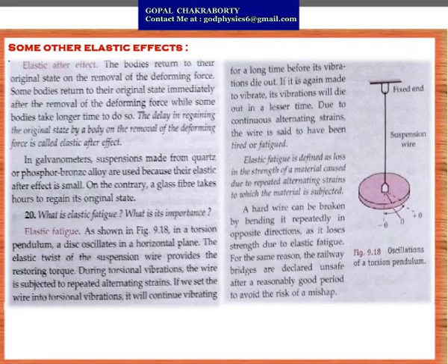Next one, what is elastic fatigue and what is the importance of it? Here the picture is shown. A torsional pendulum is considered, which is rotated through some angle theta from the mean position of rest. In a torsional pendulum, a disc oscillates in a horizontal plane. The elastic twist of the suspension wire provides the restoring torque. During torsional vibrations, the wire is subjected to repeated alternating strain.